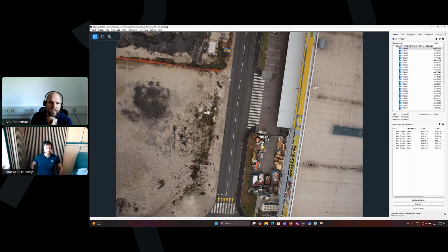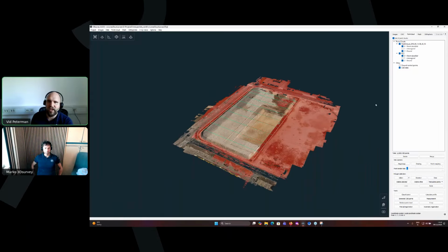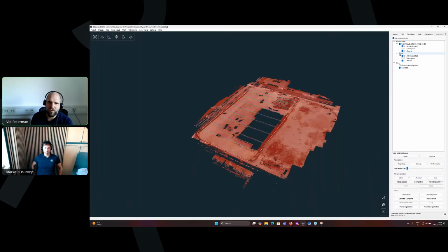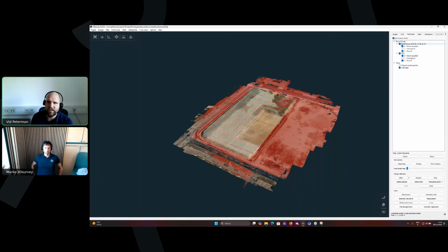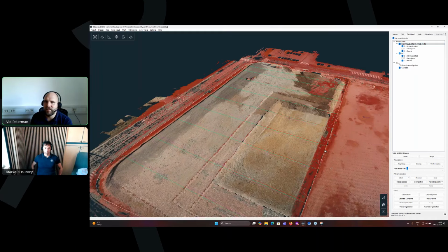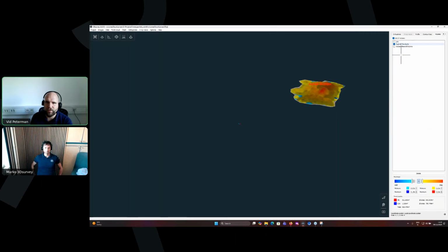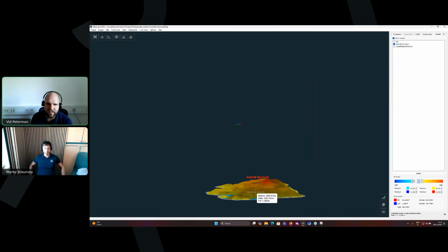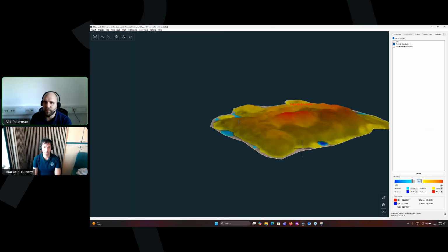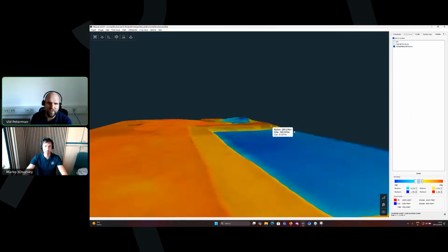Let's check this project. So here I have a small survey of an area in which I have two different point clouds. So this was measurement number 1. This second one is measurement number 2. You can see that I calculated some vertical cross sections here. And we also have some volumes calculated. So I calculated this pile of the asphalt. So this one was calculated from one surface. We also calculated how much material was added to the site, and this was the second volume calculation.